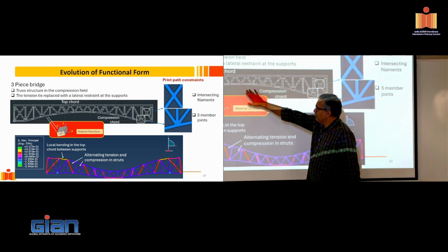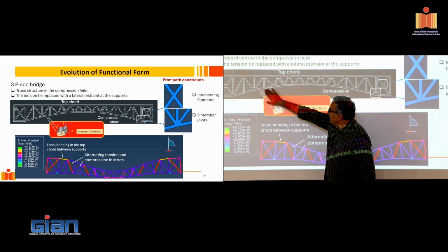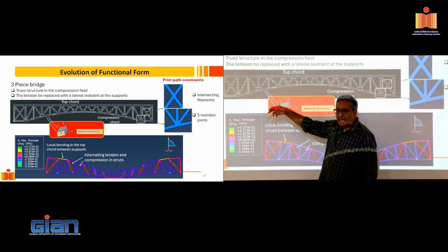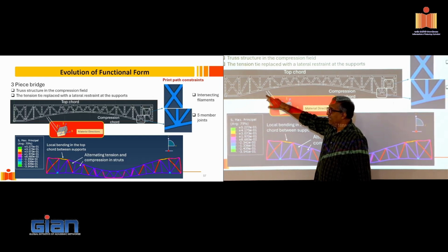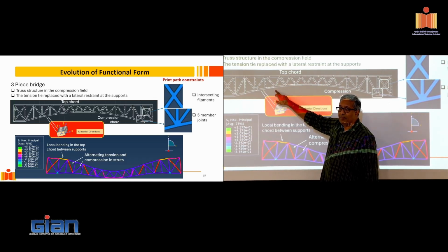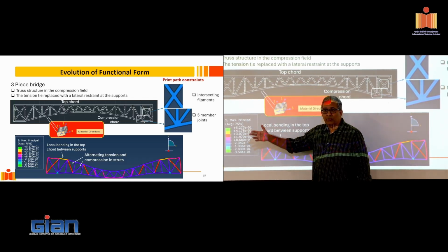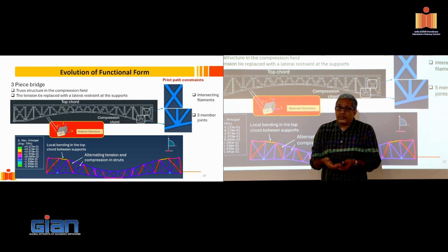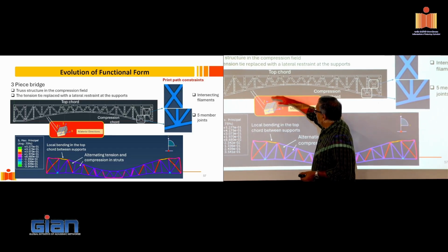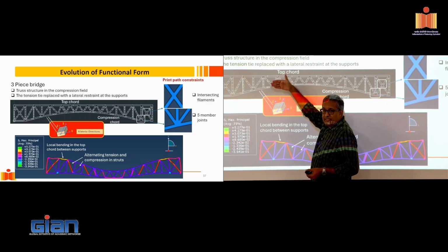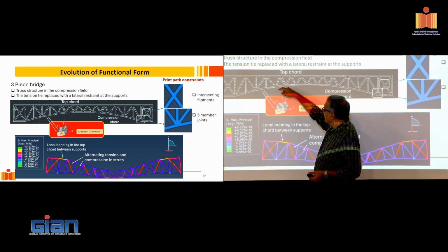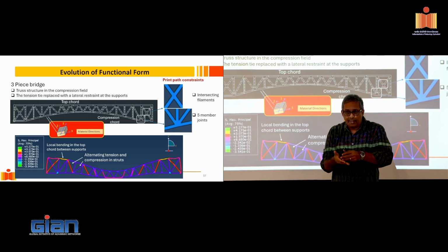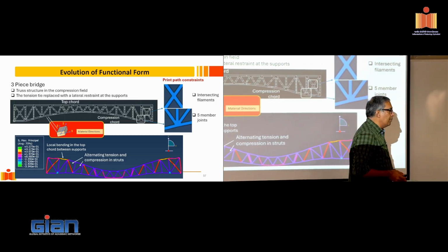Now, if you look at this particular thing, my print direction is going to be along here. How would I print this structure? The nozzle would basically move around, and the U direction is aligned with this truss element here. U is the strongest direction. So what am I doing? I'm placing my strongest direction where it has to carry the stress, right? The filaments would be stacked up in this direction here. So the weakest direction is going to be the one which makes up the layers. Okay, so that is the thing to keep in mind.